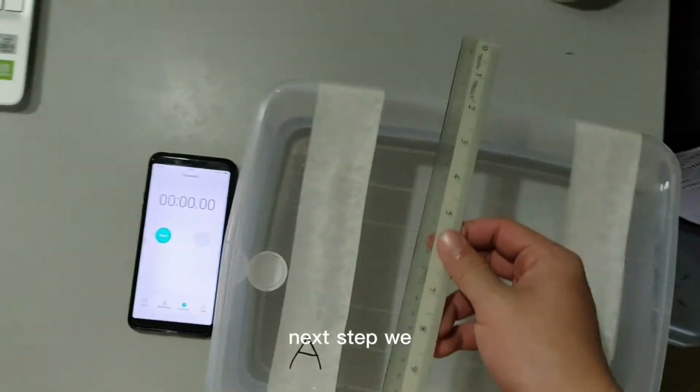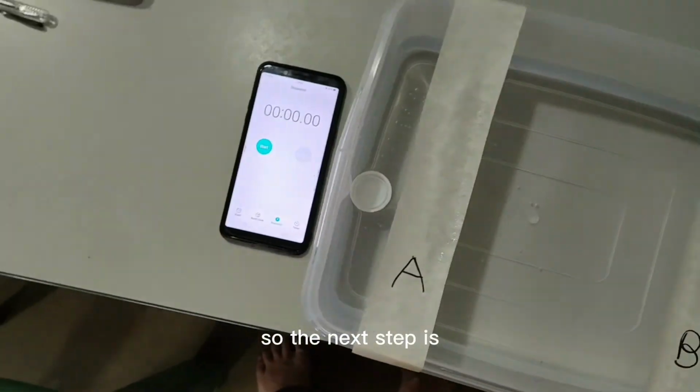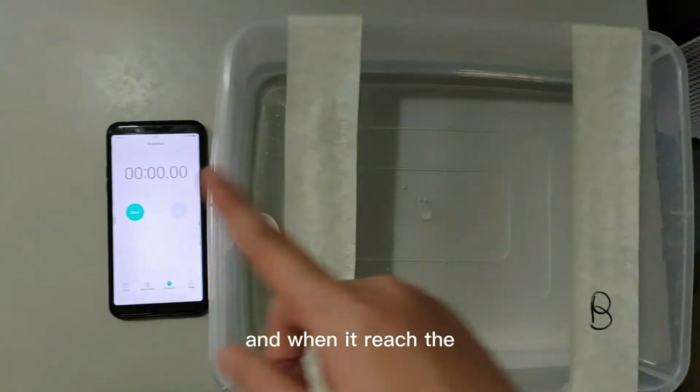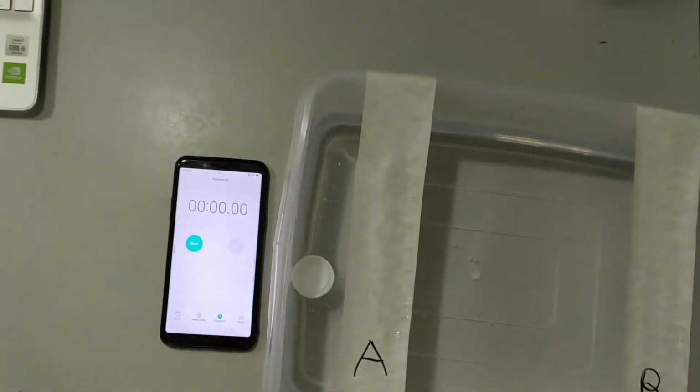Next step, we also measure the width of the stream flow. Okay, so the next step is when the cap, which indicates the floating device, reaches point A, we immediately start the stopwatch, and when it reaches the end point, which is point B, we stop the stopwatch. So let me show you.